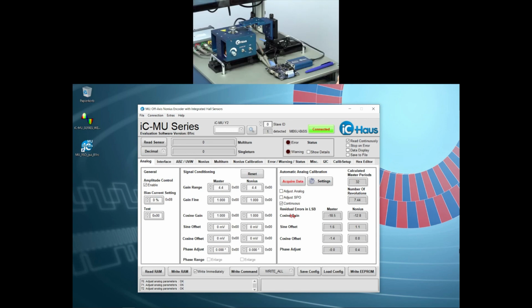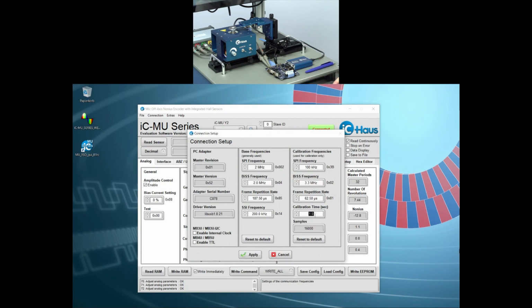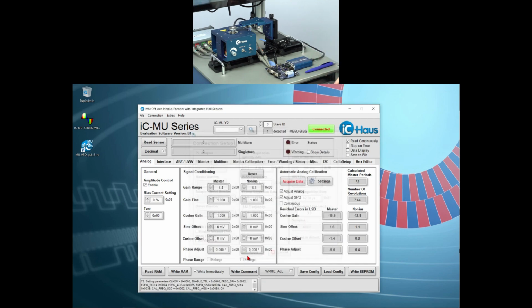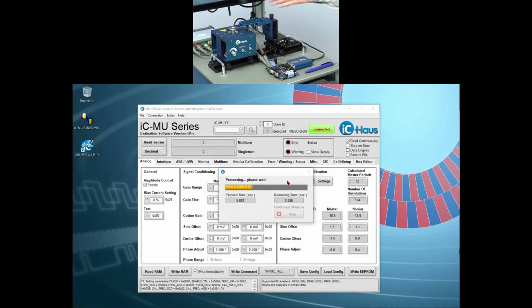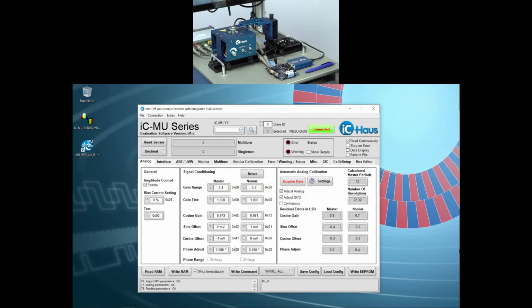And let's do another calibration run now. I'm using a little bit higher time now, let's say 3 seconds, okay? And you should see now, because I already did a perfect alignment in the radial direction, that the phase error that is compensated for here should be pretty small. All right, so you see I hit it perfectly. The phase error sits at 0. And this is, of course, very nice.